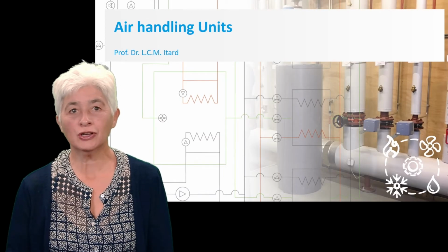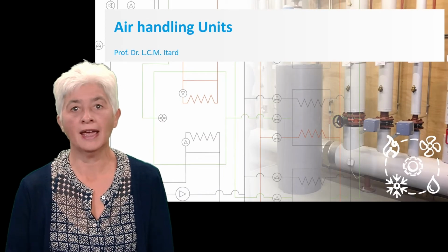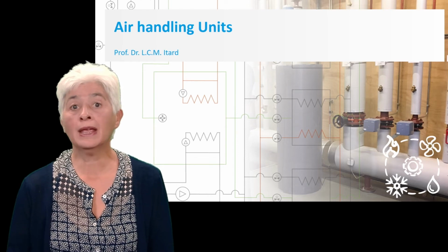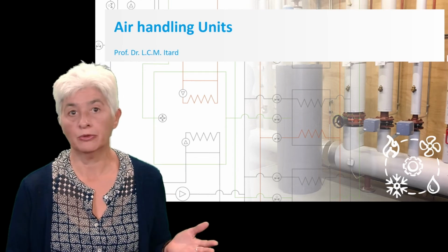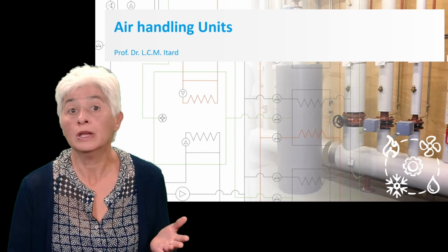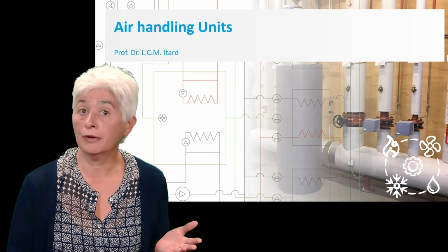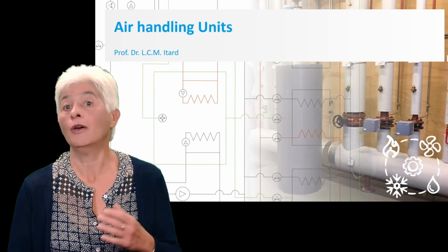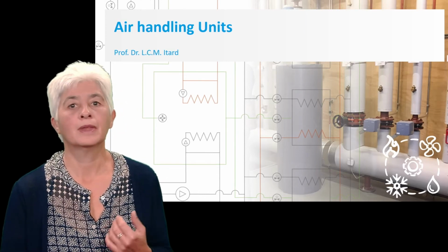Welcome to this lecture about air handling units, AHU. They are used to bring ventilation air to a comfortable state. In some buildings, they are also the only heating or cooling system present, while in others, they work as an addition to other heating and cooling systems.